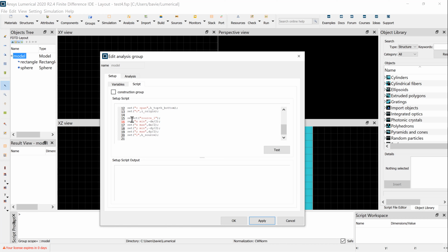After we are done with the script lines for the excitation source, we have several options to proceed further. One of them is to add script lines for another element in the simulation domain, for instance, field monitor settings. Technically, we could type all these settings at once. We would need to type commands for excitation source, field monitor, mesh parameters, and general FDTD settings. You can do all the scripts at once if you have more experience with this kind of coding. If you don't have the experience, it's probably better to type settings one by one.